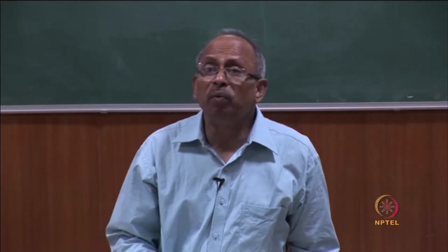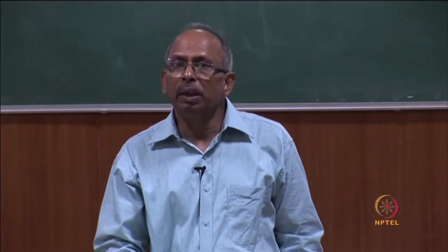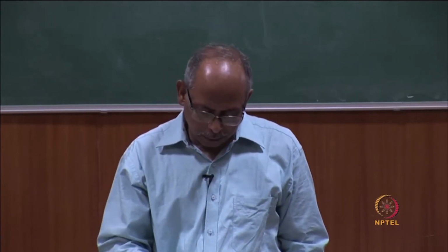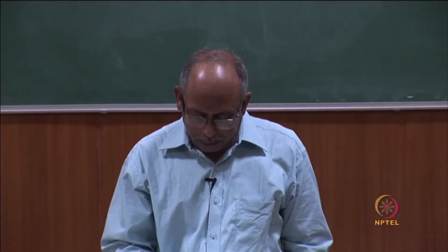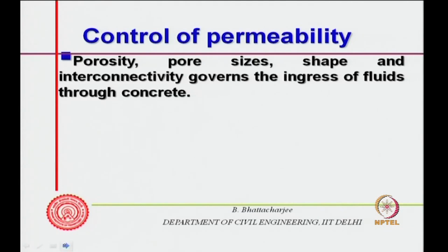So, what have we seen so far? We have seen that permeability depends upon porosity, pore sizes, shape, interconnectivity, and this all governs the ingress of fluid through the concrete. All right. So, if we want to control the permeability, we will have to actually look into these issues.